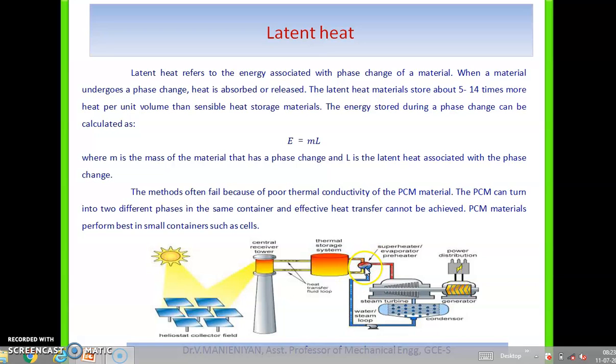Here there is a heat exchanger that changes the water into a binary solution, that is, an organic fluid. The organic fluid is converted into vapor and expanded in turbines. Again in the condenser the organic fluid vapor is converted into a liquid, and a pump recirculates it. So here the material undergoes a phase change, whether solid to liquid or liquid to vapor, and the organic fluid is used as the storage material. So that is called a latent heat storage system, that's the basic working principle.